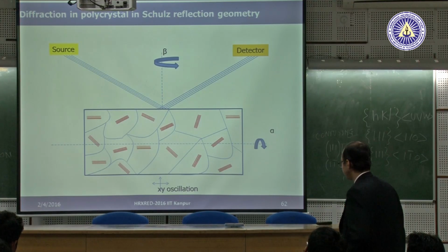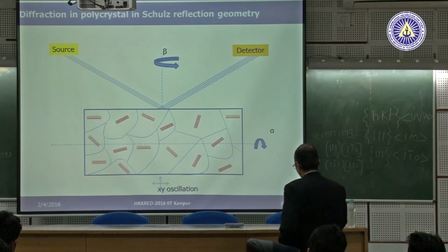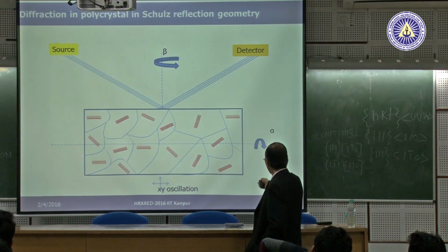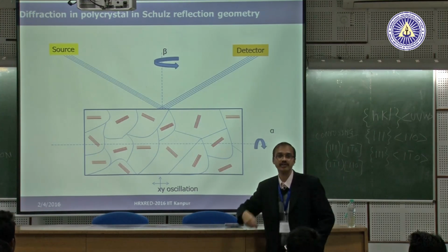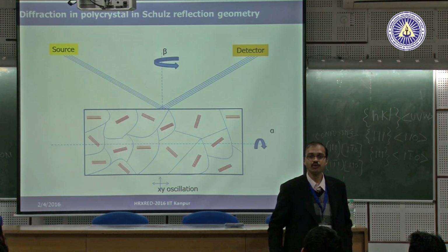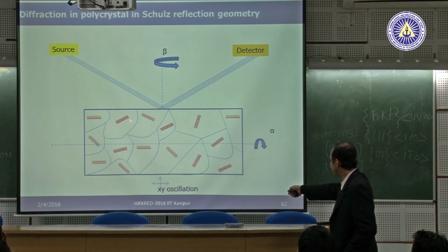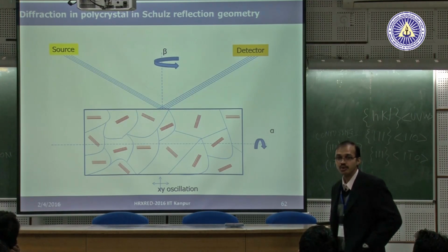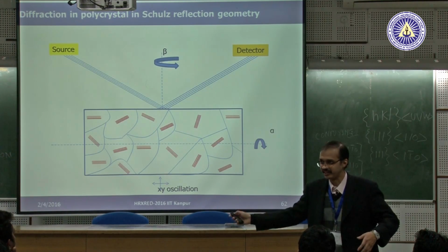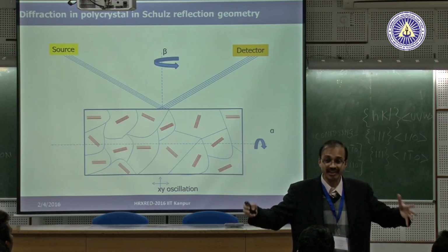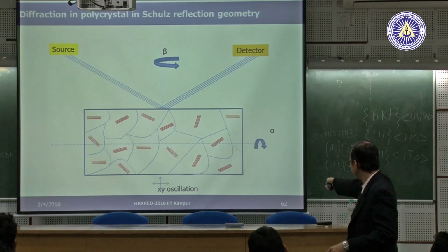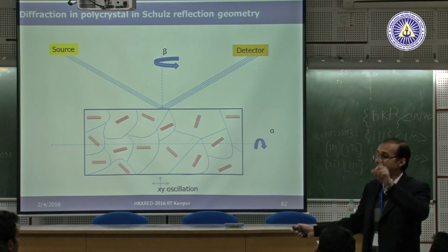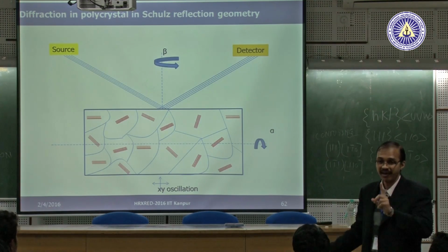And now when I do X-ray, let's go back to our Bragg's law, and you know what is going to diffract here? Only these planes, right? They follow Bragg's law. They are horizontal, so they will contribute to diffraction. These planes are not going to contribute, right? In a polycrystal, this is very exaggerated, but not all the grains contribute to diffraction. Here I have fixed my Bragg's condition. My theta here and theta here is fixed, so I'm going to call it theta b. So I go at a particular Bragg's condition.